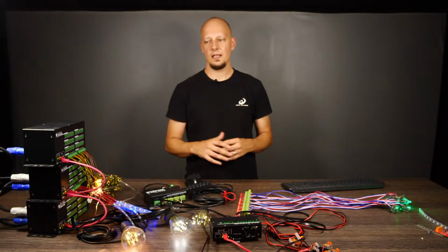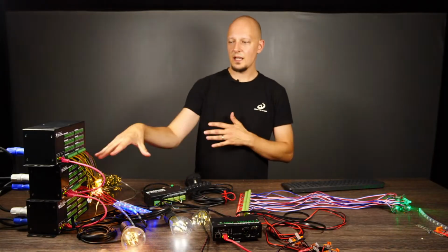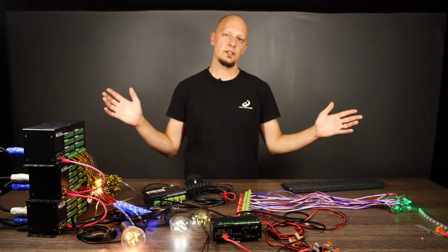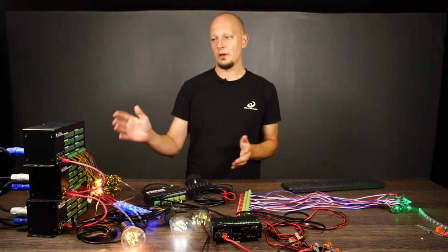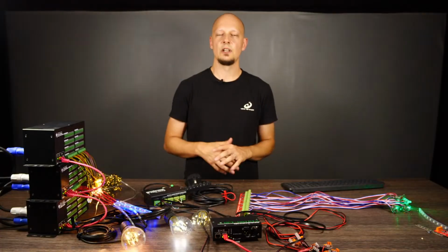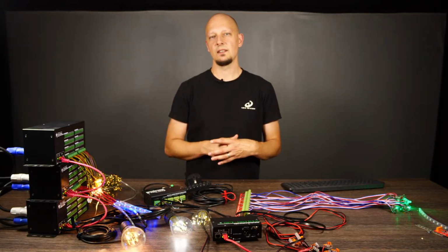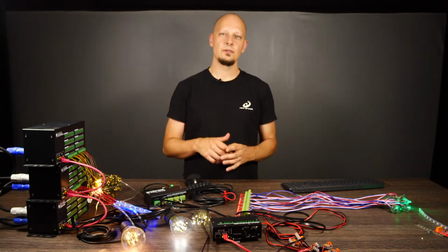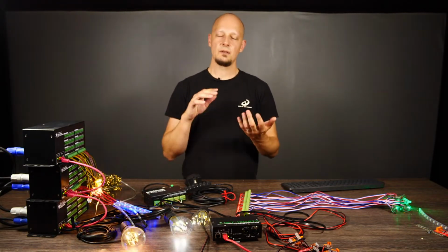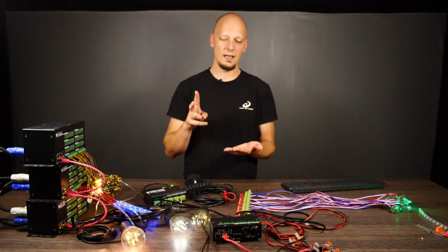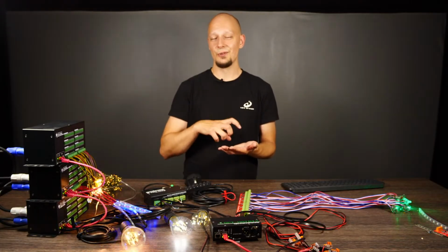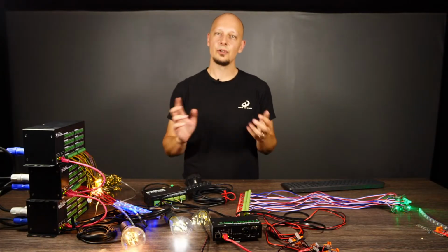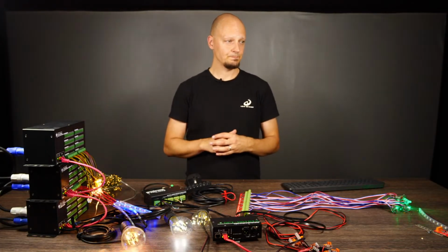Again, as with the standard powered bulb dimmers, you can have a very long distance between the controller and the dimmer, since we are sending out the differential data, differential signal. And yes, again, you can use it with third-party controllers. Just be sure that you will then also be ordering and using 2 Symmetrizers to create your differential data.